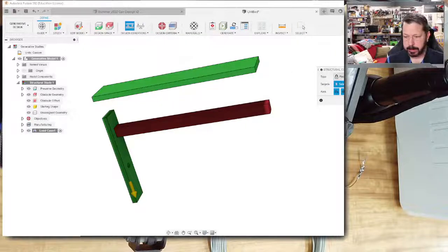So you have fixed constraints, pins, and frictionless. So you don't have as many of the types, you know, bearings and everything, but everything can kind of be summed up in these three. If you're thinking about statics and mechanics of materials, you kind of have fixed supports, stuff's welded to a wall or embedded in the ground. You've got pins and you've got rollers, and that's kind of how you summarize most of the things. It falls into one of these categories.